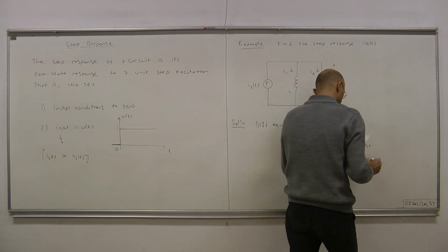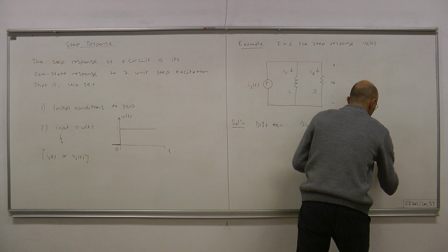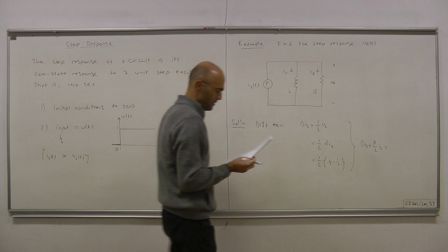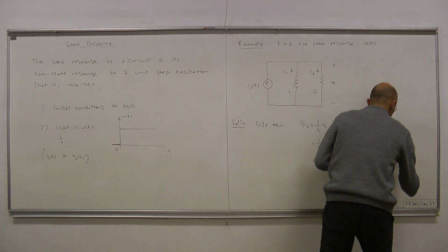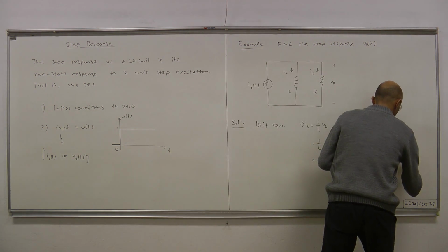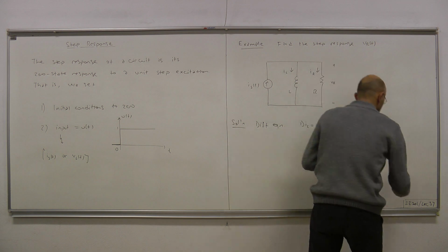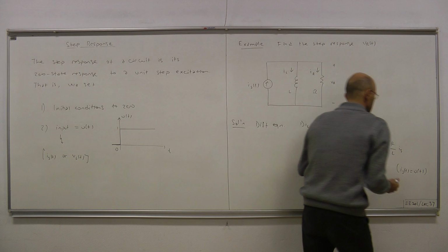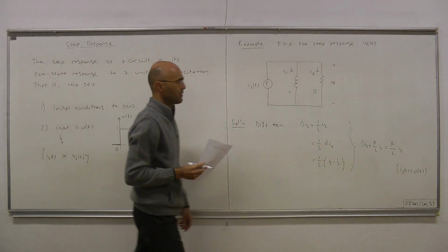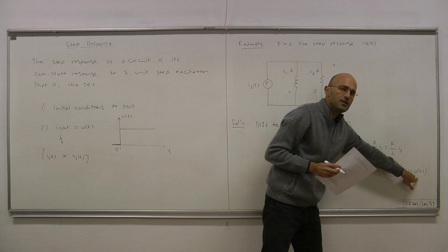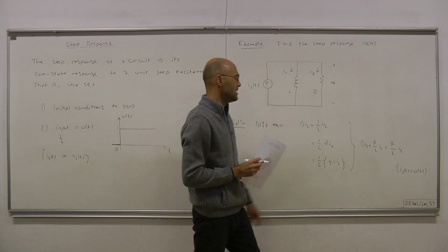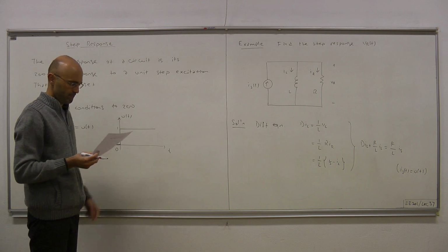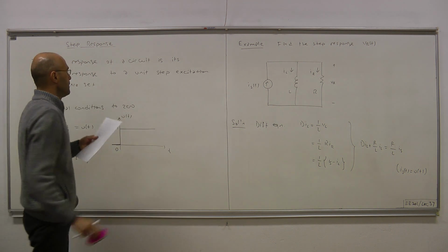Okay. So reorganizing the terms gives us what we want: di_L/dt plus R over L i_L equals the right hand side, which is non-zero because we have some non-zero input, i_S. Okay. And now we will try to figure out what happens if i_S(t) is set to unit step u(t) and i_L(0), the initial inductor current, is 0. Okay.